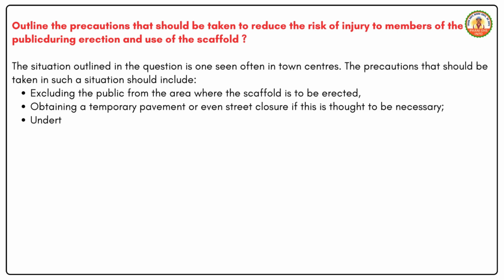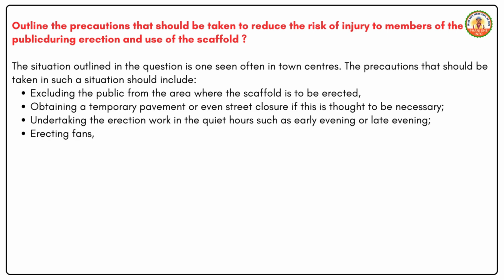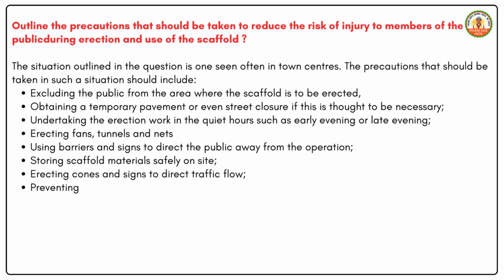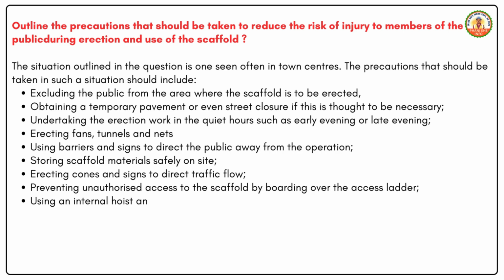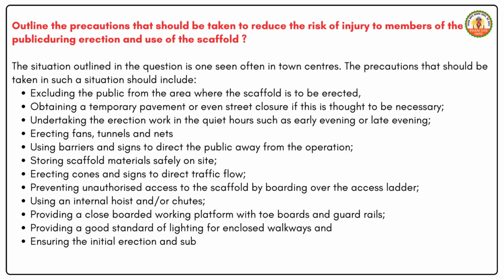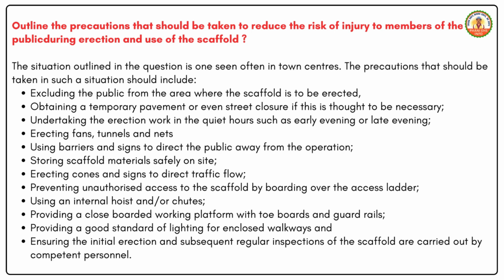undertaking the erection work in the quiet hours such as early evening or late evening, erecting fans, tunnels and nets, using barriers and signs to direct the public away from the operation, storing scaffold materials safely on site, erecting cones and signs to direct traffic flow, preventing unauthorized access to the scaffold by boarding over the access ladder, using an internal hoist and or chutes, providing a close-boarded working platform with toe boards and guard rails, providing a good standard of lighting for enclosed walkways and ensuring the initial erection and subsequent regular inspections of the scaffold are carried out by competent personnel.